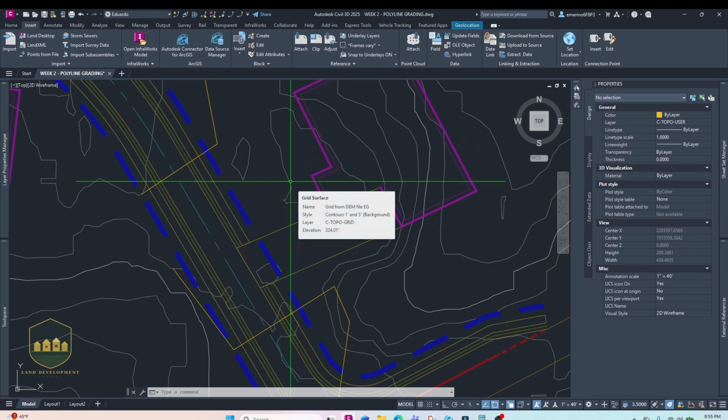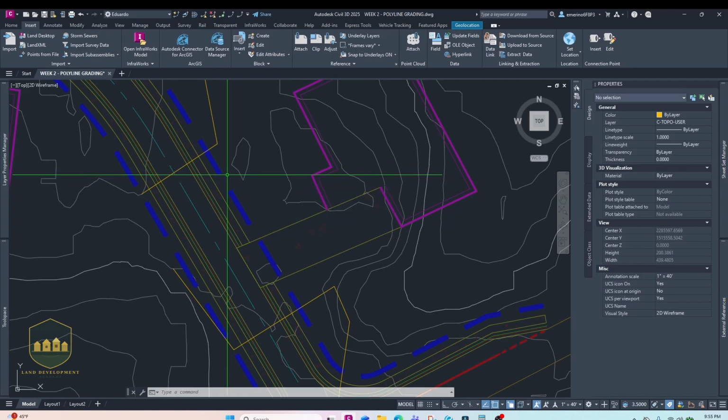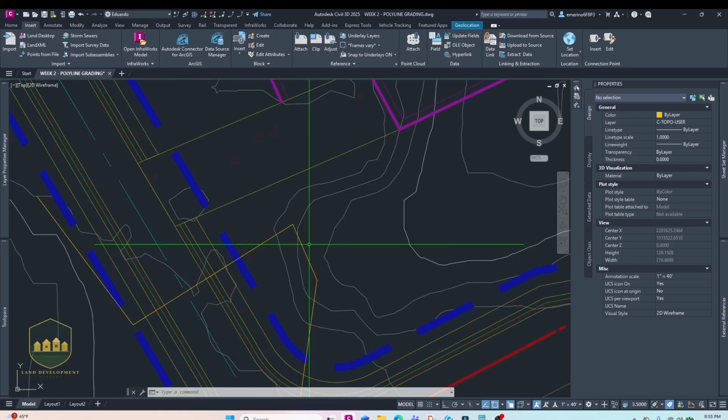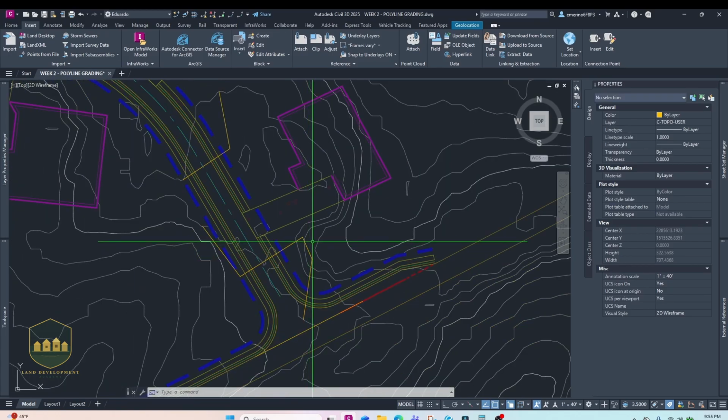But I really hate that design because now you're reliant on those inlets to not fail. And if they fill up and a massive storm comes, they fill up or they get clogged, now you have water bypassing that inlet and going into the house, which can lead to flooding. And if I can do something about that to avoid it, I will.